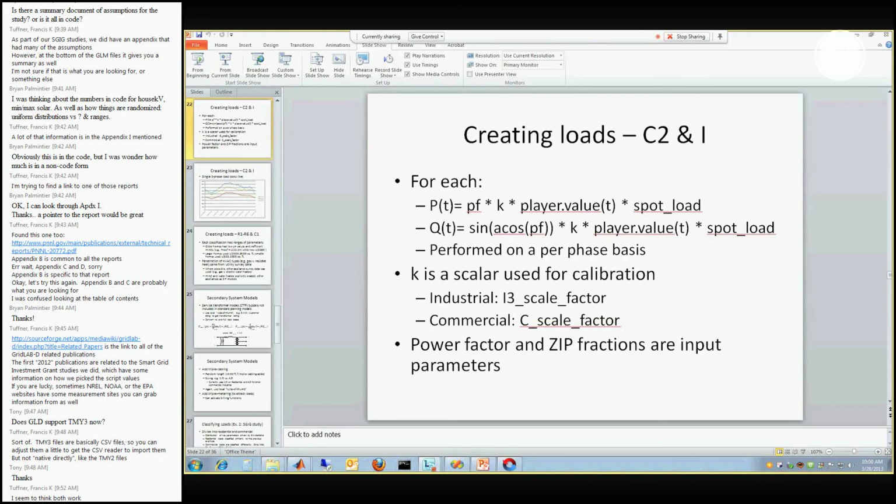And just to confirm, with going off our SCADA data, the algebraic sign that's associated with the Q, what we recorded on the SCADA data source, if it's normally negative there, then the load should also be negative. Correct, yeah. Yeah, the power factor interpretation. Right? Yep, exactly.